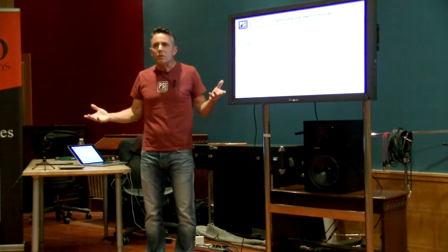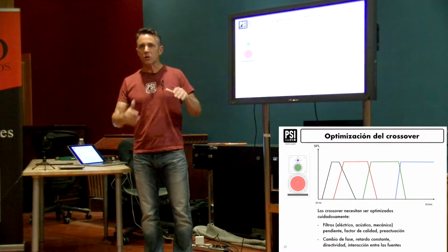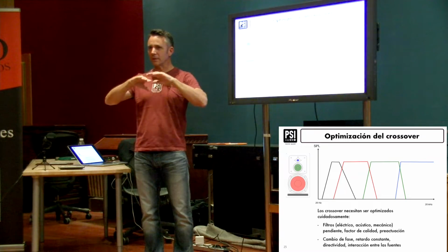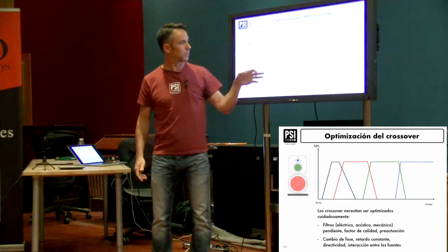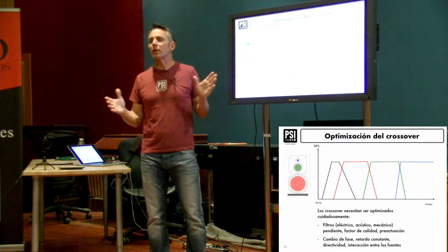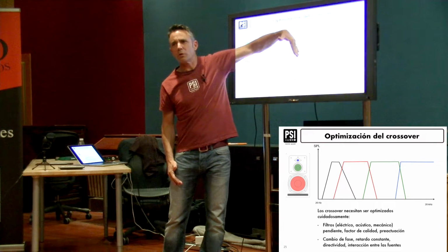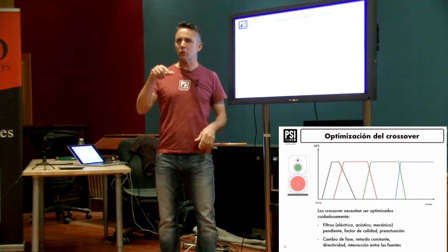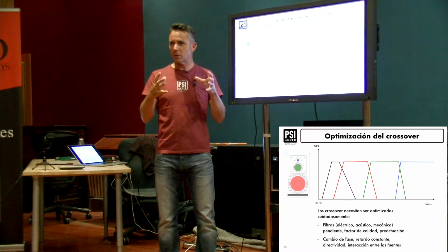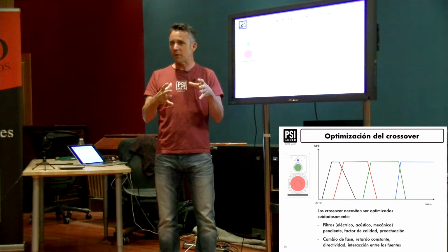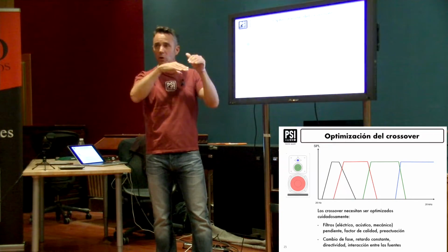One of the key elements is how to get this and this aligned, so that what comes out is perfectly in frequency and phase. I think you explained a lot of it, but it's what we call the crossover. You can play with different things in these crossover filters. You can play with the slope, that's what order filter you use. Remember that there's not only the electronic filter, there's also the acoustic or mechanical filter from the driver itself. So you tend to use a bit of both so that they work together.